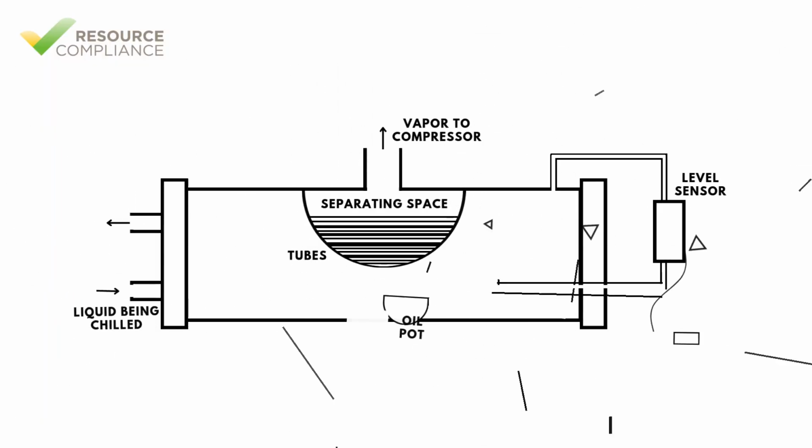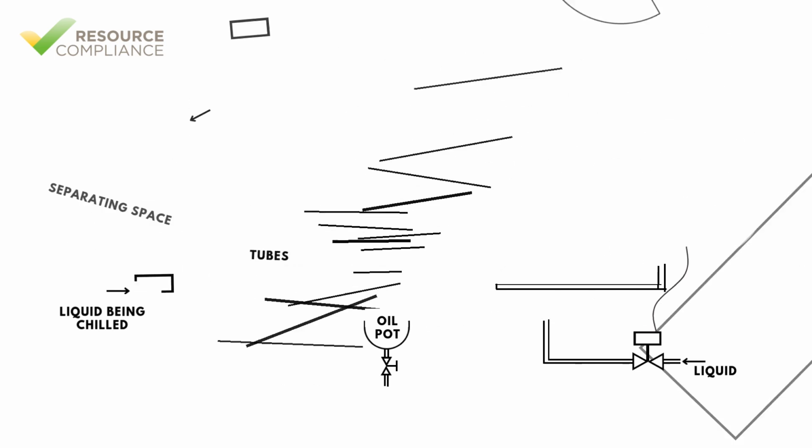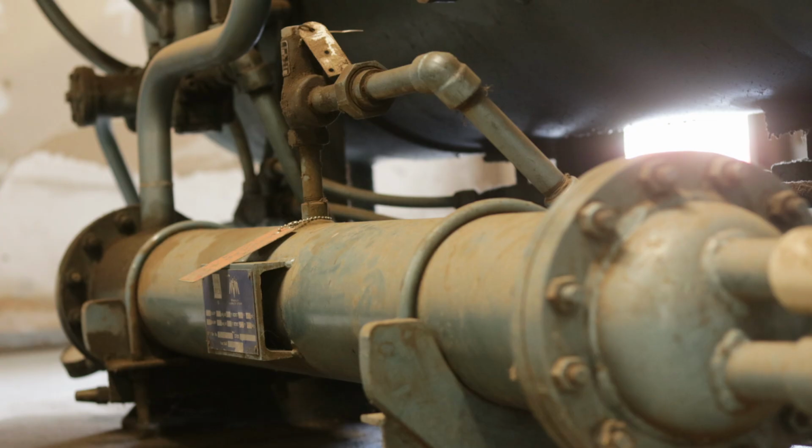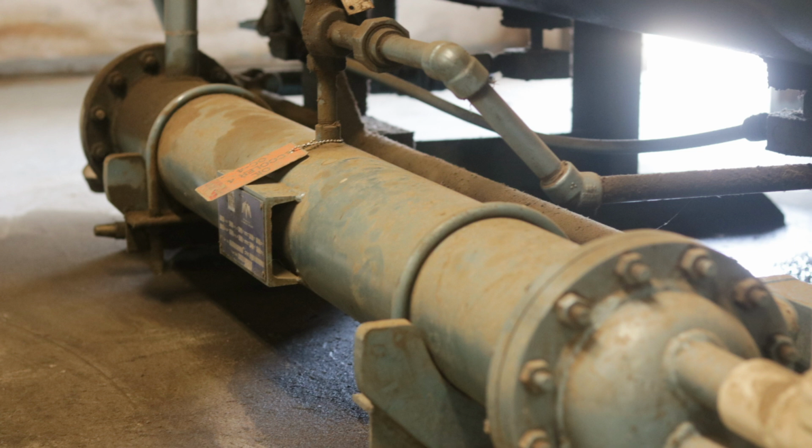In most refrigeration evaporator applications, low-pressure liquid refrigerant is supplied to the shell and the fluid is pumped through the tubes. Heat is transferred from the fluid through the tube walls and into the refrigerant within the shell. As the refrigerant absorbs heat, it evaporates and is returned to the compressor. Sometimes refrigerant is supplied to the tubes and the fluid being cooled is in the shell. This combination is commonly employed in shell and tube oil coolers on screw compressors. Refrigerant is supplied by the thermosiphon receiver to the tubes and exchanges heat with the oil inside the shell.